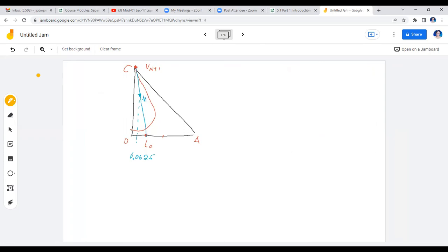So the 0.03 or the 3% acetic acid in the raffinate, you locate again in here. So this is 0.05, 0.06, so this must be 0.03, just on an approximation. And what will you do with the 0.03? You project it up in here on this part of the phase envelope. This one has an X sub A, N, which is 0.03. You locate the 3% here on the horizontal axis.